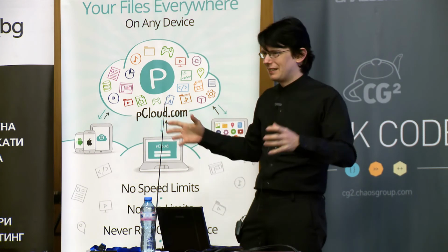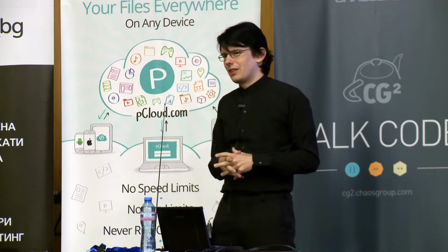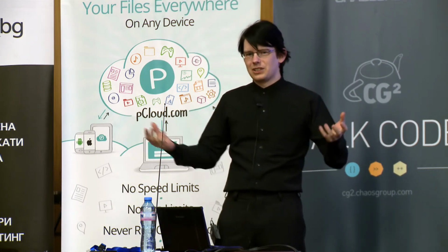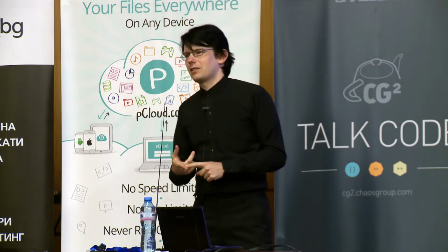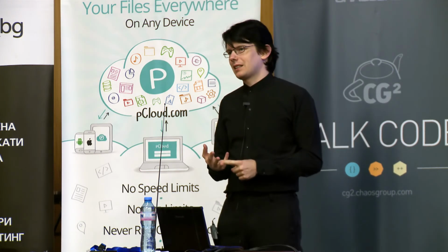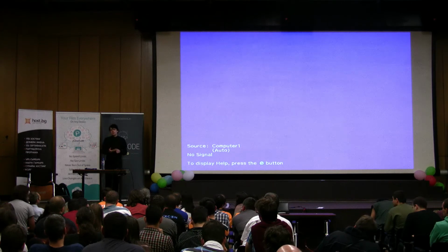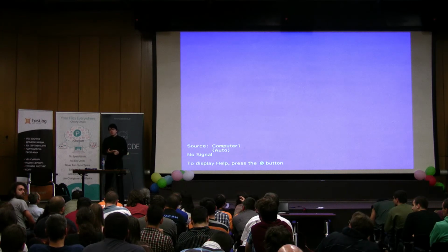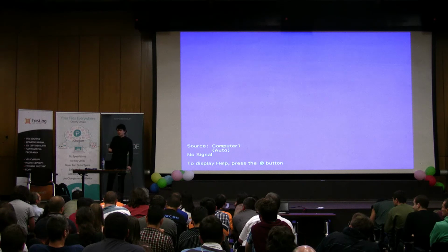One other interesting system that you can listen into, you need a satellite dish for this though, is the Thuraya satellite telephony system. There's an Osmocom project called Osmocom GMR by which you can receive the satellite communication. The encryption has been broken for several years. The voice codec has been reverse engineered. And the interesting part about Thuraya satellite phones is that by the protocol specification, every phone that makes a call must transmit its complete GPS position at the point you attempt to make the call. So the call cannot be made unless you include the full GPS position of the phone.